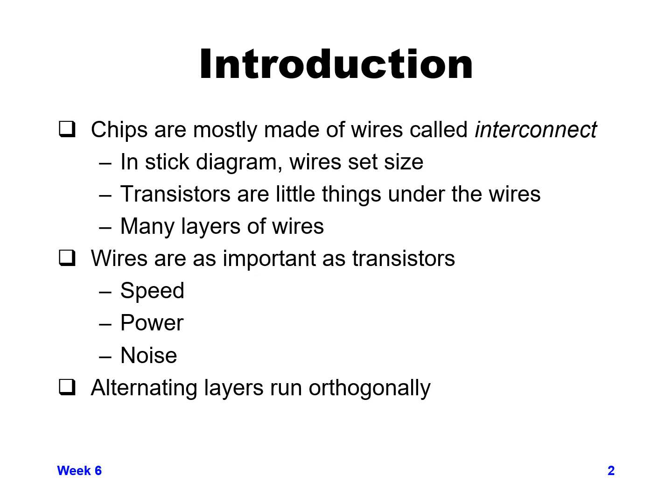As I mentioned previously when we were talking about process technology, the wires tend to alternate, so alternating layers run at 90 degrees to each other. So your metal 2 might wind up running horizontally, and your metal 3 runs vertically, metal 4 again horizontally, metal 5 vertically, and by alternating what direction each layer runs, you can make the best use of your metal in order to get signals to the areas that you need to go.